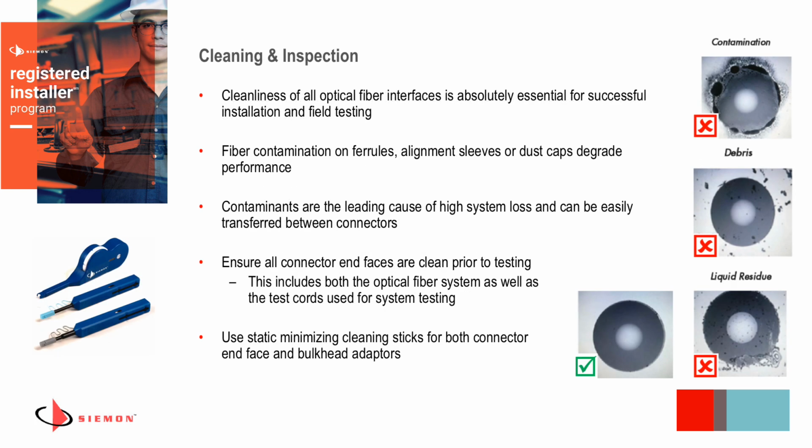As mentioned previously, the cleaning and inspection of fiber is so critical to the overall system performance, as nearly all field issues are somehow attributable, usually, to the cleanliness of the end faces of the fiber. So if you want to have some success in installing fiber systems, you have to make sure you have the means to both inspect those end faces as well as have the proper cleaning tools to ensure that they're cleaned properly and inspected before being tested.